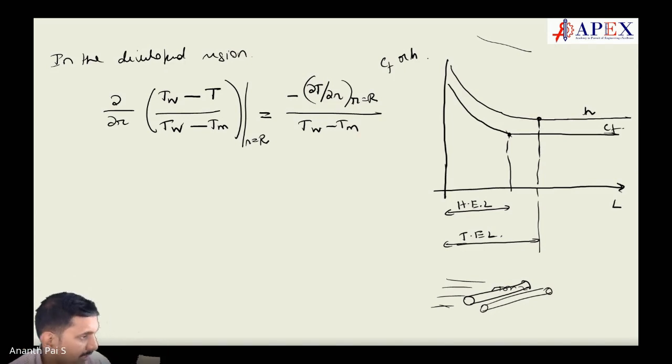Ti varies as it goes through the pipe. This understanding has to happen. Ti is the average velocity and average temperature. Velocity remains the same. Whatever the average velocity is, from the starting till the end, it remains the same. Why? A1 V1 is equal to A2 V2. Temperature is not that case. So there are complications on the temperature.